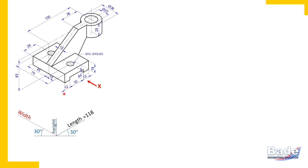Now overall width, with reference to this position of observer, this is front side and this is back side. So from front to back, extreme front surface to extreme back surface, length is given 75 mm. So overall width of the object is 75 mm. Now check dimension vertically. Parallel to height axis, 63 mm is mentioned here. There are many other dimensions which are parallel to height axis. But remember, we need dimension from extreme base to the top. And from base surface to the top surface of the object, already height is given 63. So this is how we have identified overall dimensions.